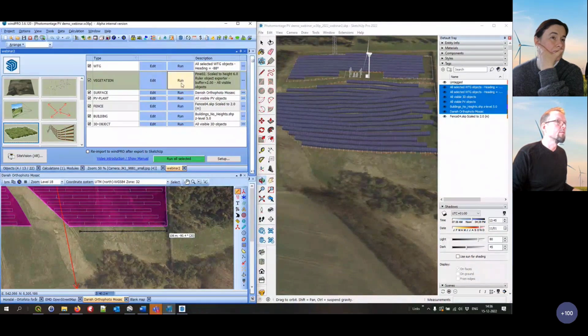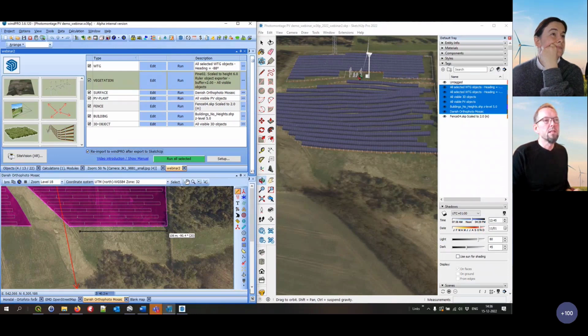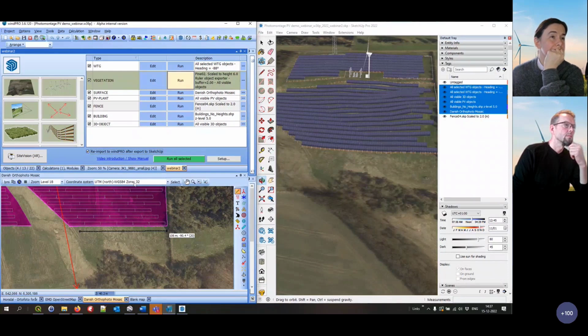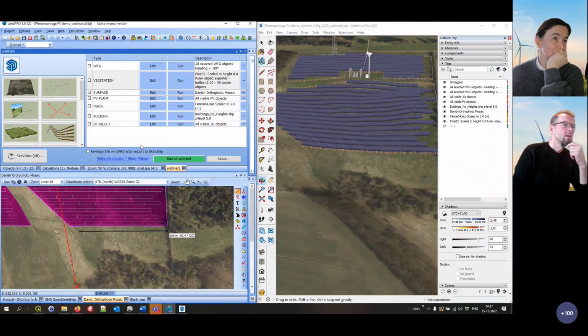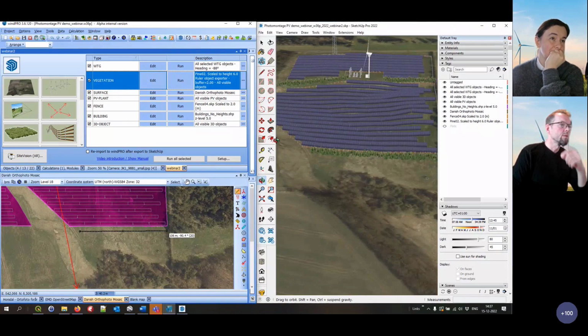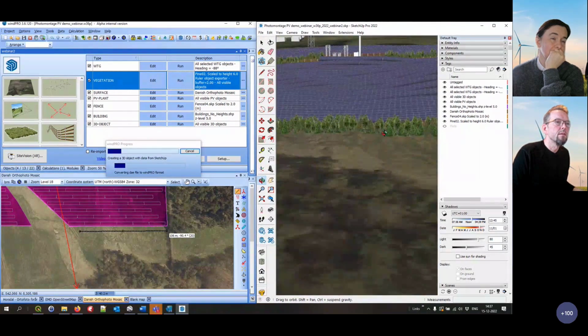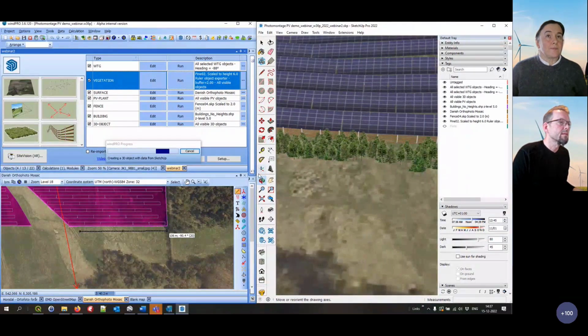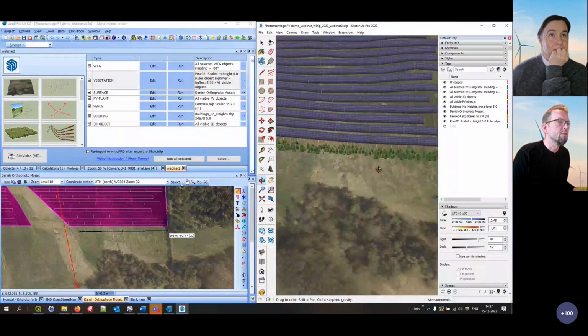And then I just run this vegetation export. Oh, this time I will show you something smart. You can actually click this re-import to windPRO after export to SketchUp. Then I don't have to go and select it all in SketchUp and say export to windPRO. Then it will do that automatically after I run the exporter over here. So I'll just try and do that. So now windPRO is done. And yeah, so now actually you can see here all the vegetation, and it is already selected and being exported back to windPRO.